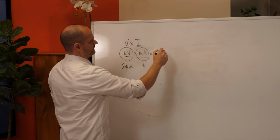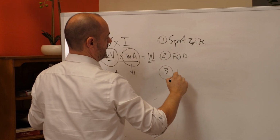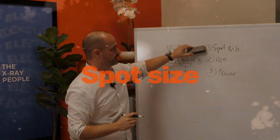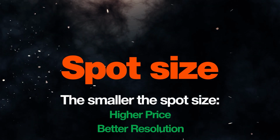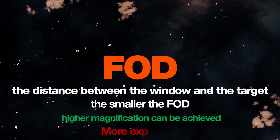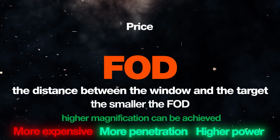So three parameters: spot size is one, two is FOD, three is the power of the X-ray tube, and that's, in summary, the principal parameters to define price and performance of an X-ray tube. Spot size: the smaller the spot size, the higher the price, the better the resolution of the image. FOD, that's the distance between the window and the target: the smaller the FOD, higher magnification will be achieved, the more expensive the tube gets. Power, similarly: the higher the power, more penetration you're going to get, more luminosity you're going to get, but at the same time, price also goes up.